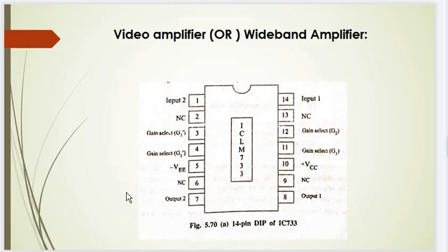It has the ability to provide a frequency bandwidth of 120 MHz, and it offers an input resistance of 250 kilo ohm. External frequency compensation is not required, and it provides a high common mode rejection ratio at higher frequencies. The selectable gain values are 10, 100 and 400. The IC is used in magnetic tape systems or disk file memory.